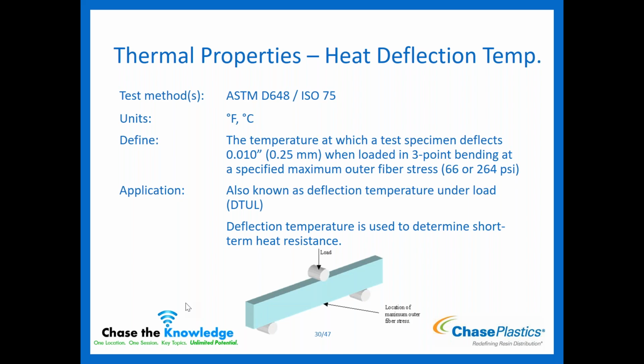So if I put a load on it, the temperature slowly rises, and then eventually when it deflects that 10 thou, it's going to take that temperature reading, and that's the HDT value for that material. So I know for good short-term heat resistance performance, if I'm utilizing a temperature that's quite a bit below HDT, I can go, I'm probably really good at that temperature.